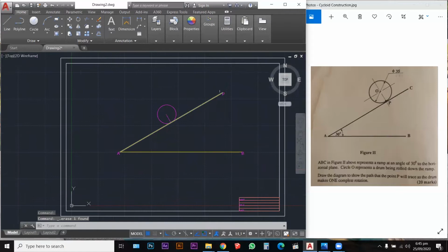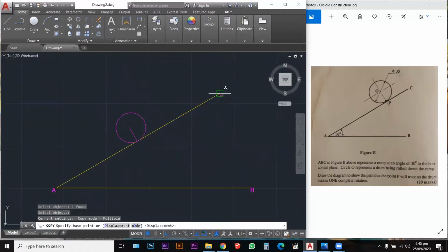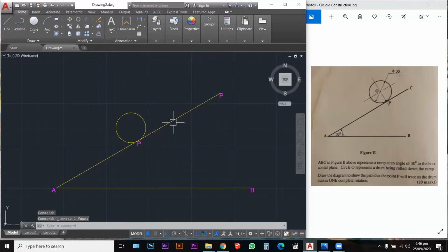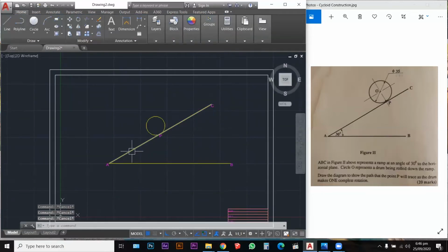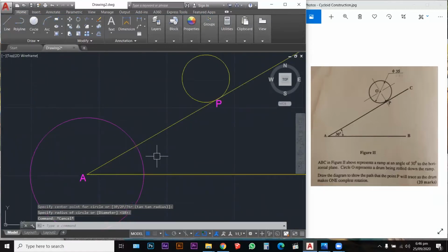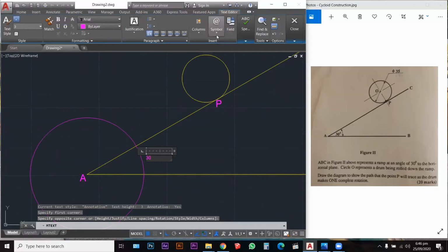Okay, good. So I have actually located where my P is, and my circle that is 35 millimeter diameter. So everything is in. We are ready to solve this. So this line point here now would go to C. So I have it set up. That is the setup. And so that you guys can understand what I've done, I'm actually going to place the 30 degree in here. MText, I'm going to put 30 degrees. And the symbol for degrees is right here, 30 degrees.